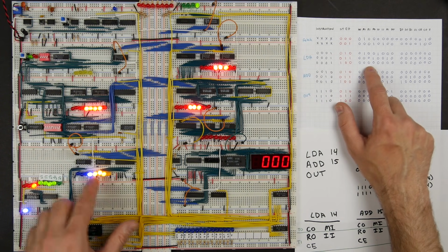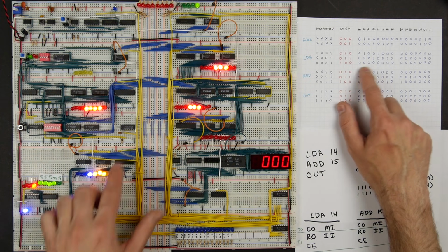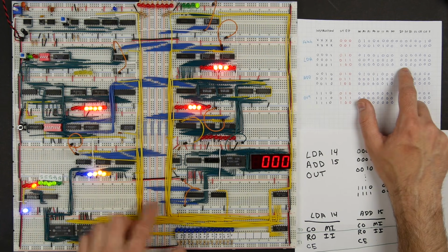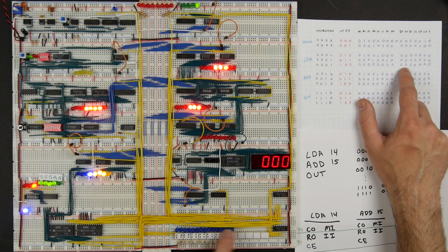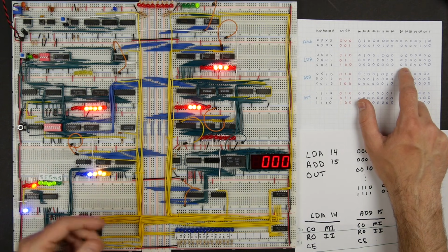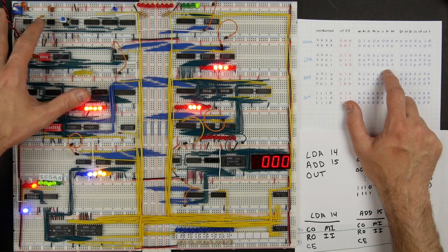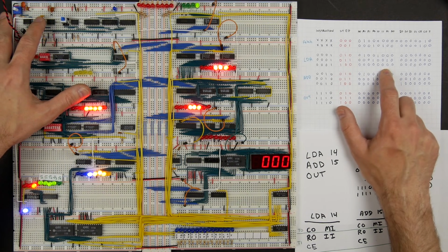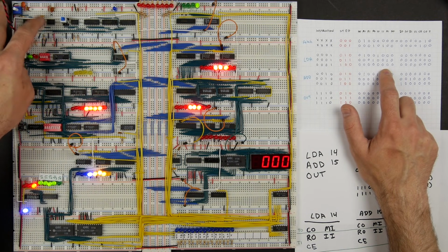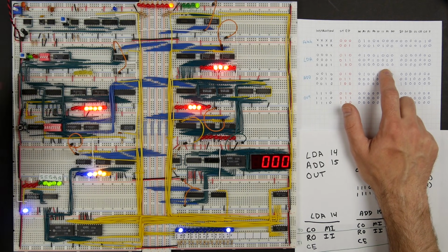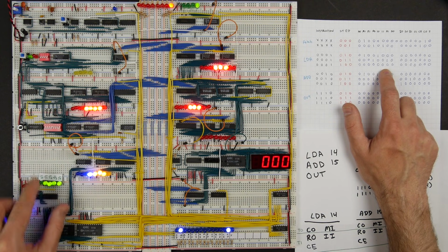And we're done with the load A. We've loaded that 28 into the A register, so we don't need to do anything. So this step basically doesn't do anything. So there's nothing set here. So it's really just kind of a waste of time, if you will. But maybe there's a way to optimize that in the future. But for now, it's okay. We'll just use an extra clock cycle to advance the clock, and nothing will happen. But we go back to time t0.